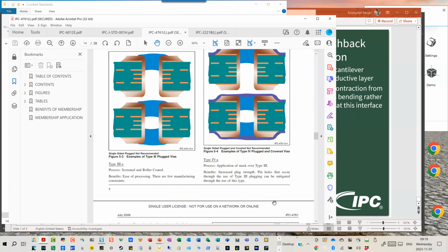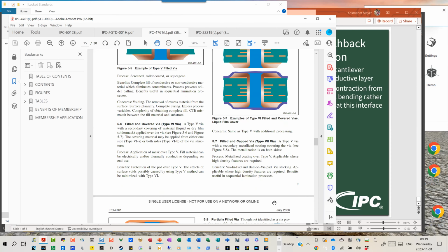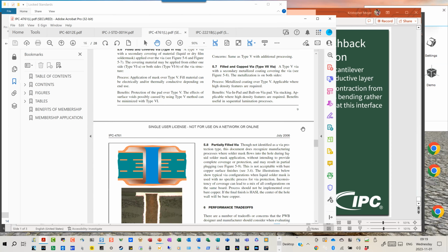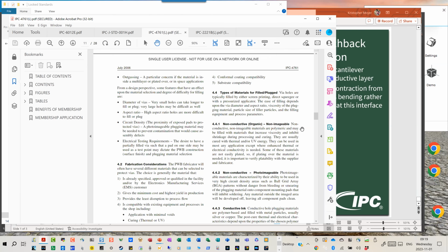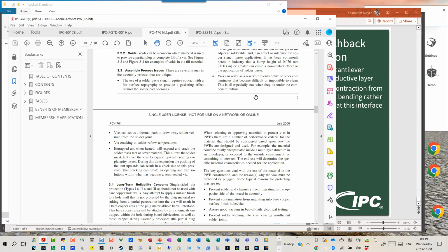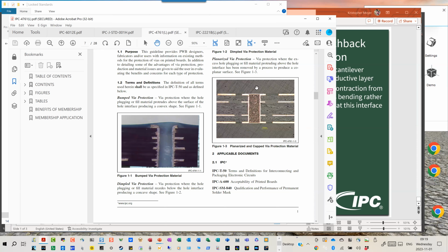Additionally, do I ever use the conductive plating material here? In fact, we have actually a picture of it up here at some of the example pictures up here where you can see copper or other particulate embedded in the resin there. Honestly, if you design your vias correctly, like I showed you guys in week 1 or week 2, where we did the via barrel sizing for the current handling, then there's no need for the more expensive plugging material with the conductive material in there.